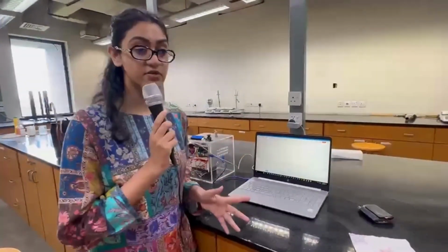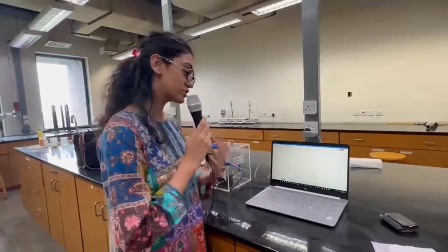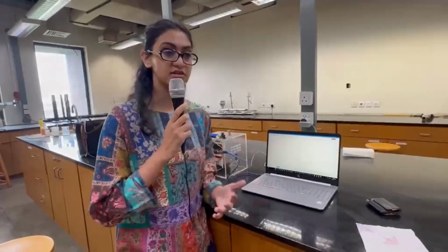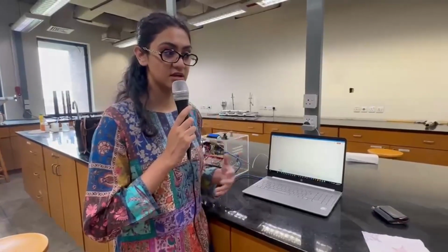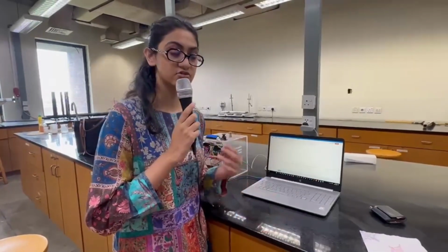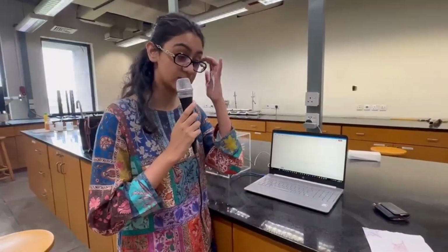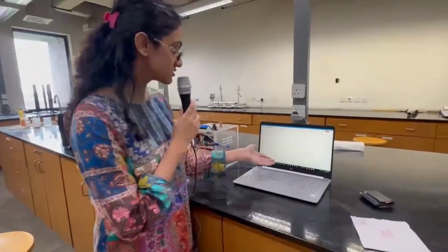And the derivative control then comes in, and what it's doing is that it's looking at the rate of change of the error in the past, and it's predicting what your error will be ahead, and it's controlling that, and that helps make it more stable. So you can see our system right now is quite stable.